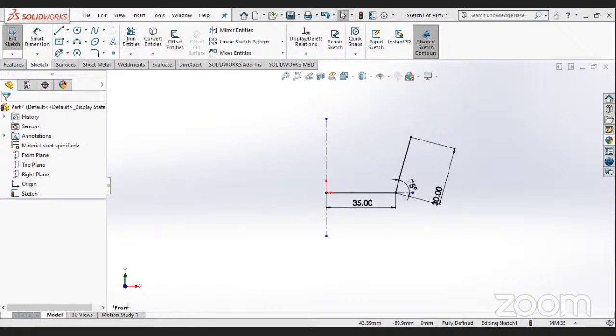So you'll subtract 6 from 20, it will be 14. So we'll make a straight line of 14 and try to make this curve with the given direct dimension, radius as 1.5.